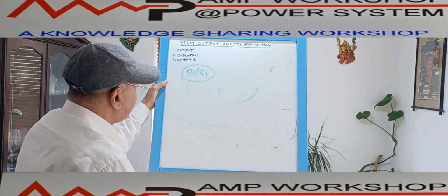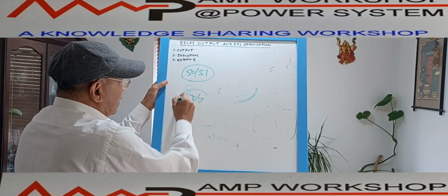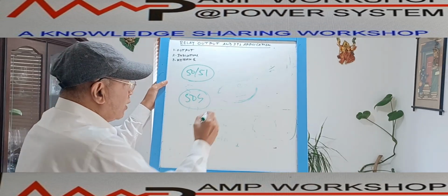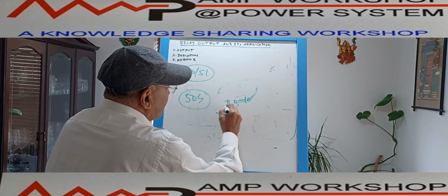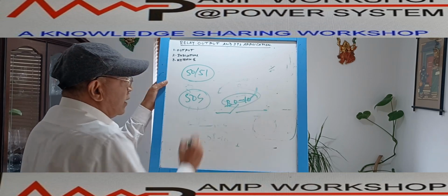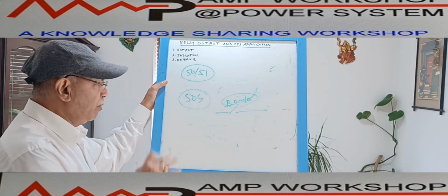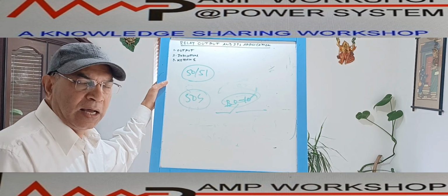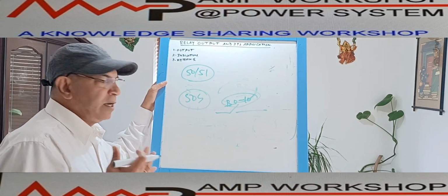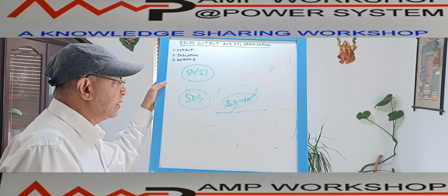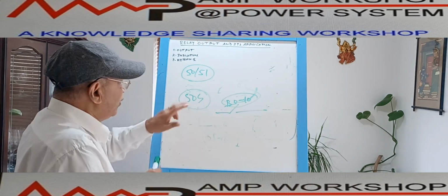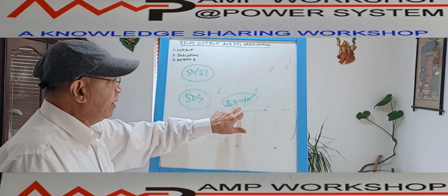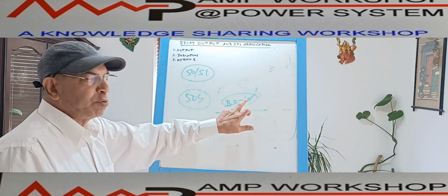When the 50G operates, suppose all of the output contacts, suppose it is binary output 10, is activating. Suppose we are programming it so that the moment the main protection relay senses the CBCT supply, and the unbalanced current comes above the setting value, immediately 50G will be operating. This 50G will be activating this binary output 10.